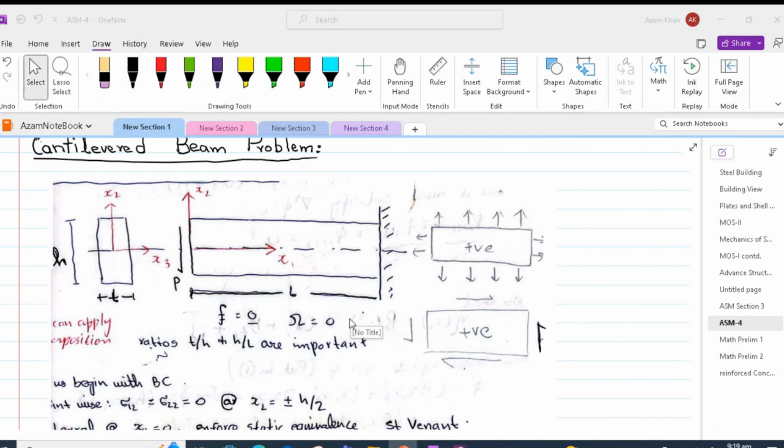We have to implement the static equivalence, which means that the Saint-Venant principle has to be applied. Thus, at the point of application of the load, it is not possible to get the actual representation of the internal stresses and displacement. Theory of elasticity will be able to give us the actual representation at some distance from the location where the disturbance is happening.